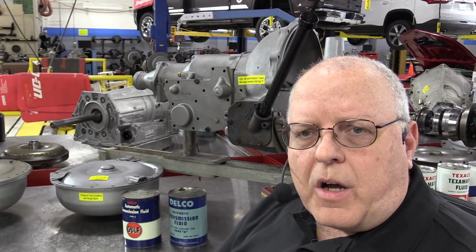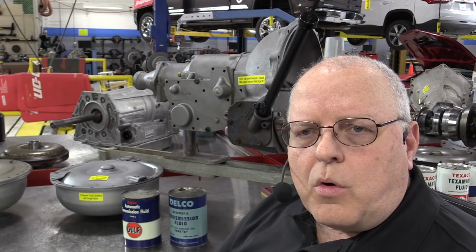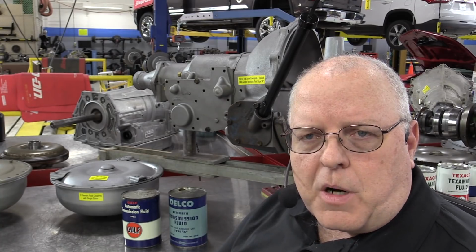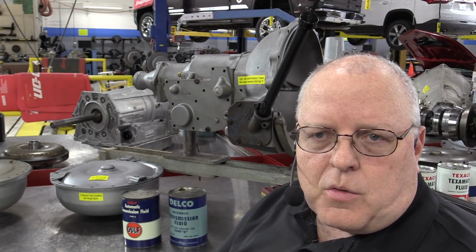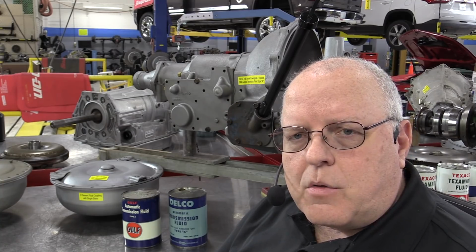So starting with 1949, the licensing and testing program was set up with General Motors, and it's been used ever since. It's not the same company doing the qualifying today, but there are companies that are doing that for General Motors. Okay, I forgot to mention on the Type A fluid that the service interval increased to 15,000 miles from the 10,000 or the 12,000 that was used on the previous Hydra-Matic transmission.